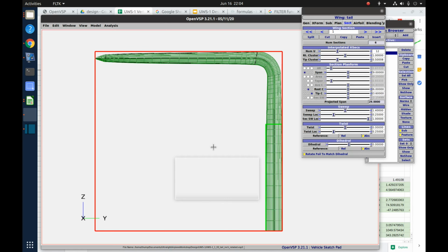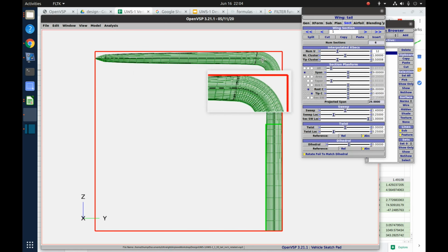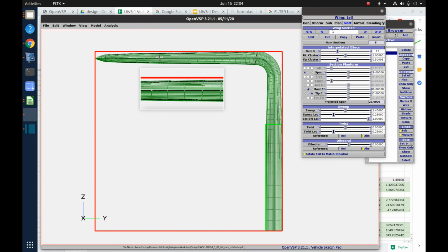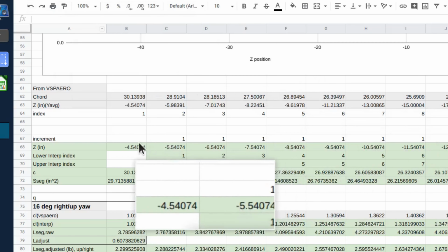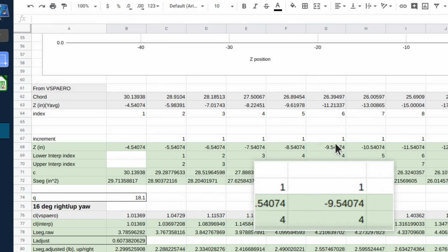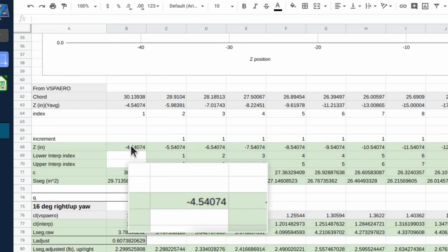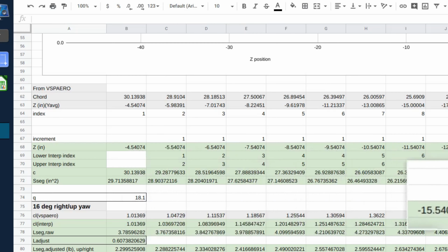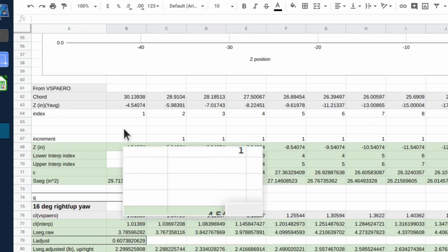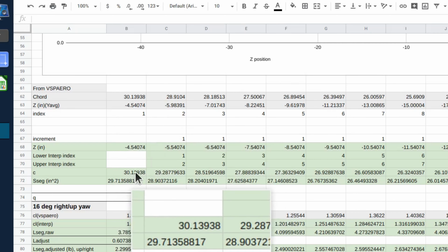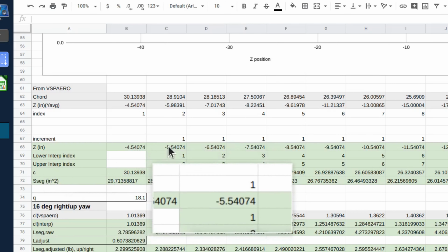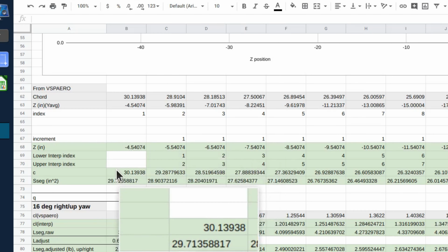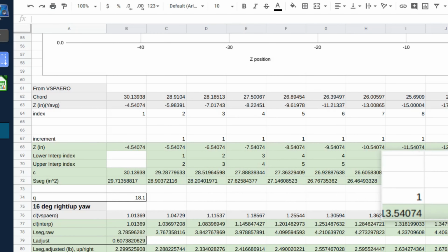But for some of the work I'm going to do now, I didn't want all this odd spacing on these Z values. I wanted uniform spacing. So I did some interpolation across these Z values, and I want to have a new Z value every inch. So starting at the -4.5 inch, every inch I create a new Z value by interpolating the old ones. And then at those new Z values, I interpolated a new chord. So with this new chord value, I came up with a new segment surface area. They're 1 inch wide in the depth of the chord, and I did that all along the vertical tail. It just makes it a little bit easier to deal with some of what we're going to do on down lower.